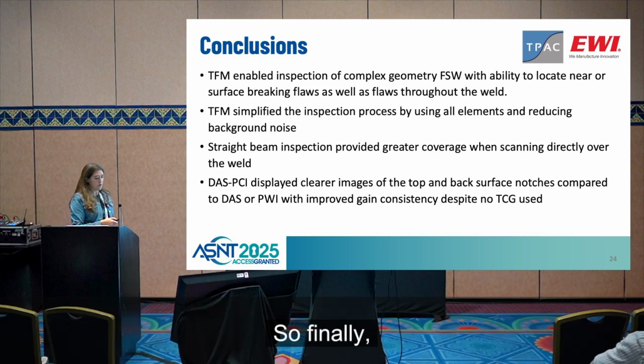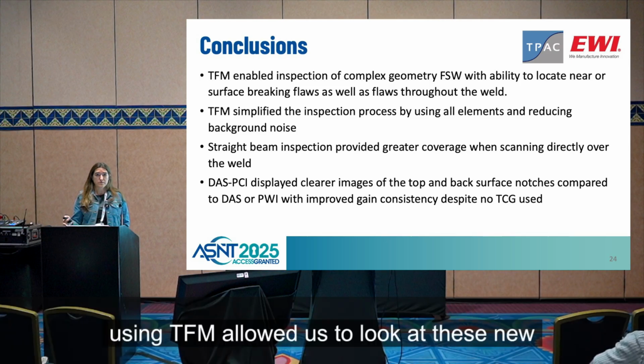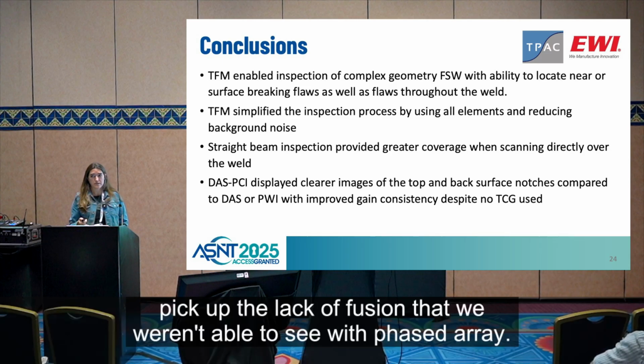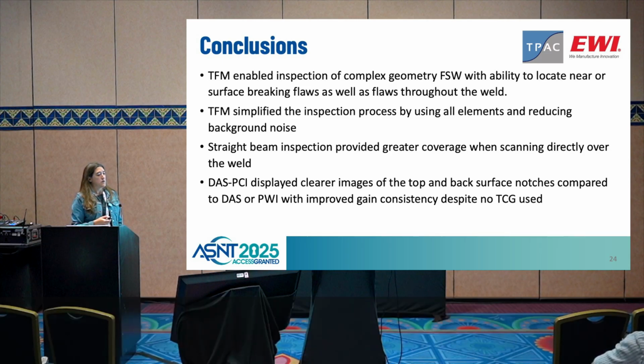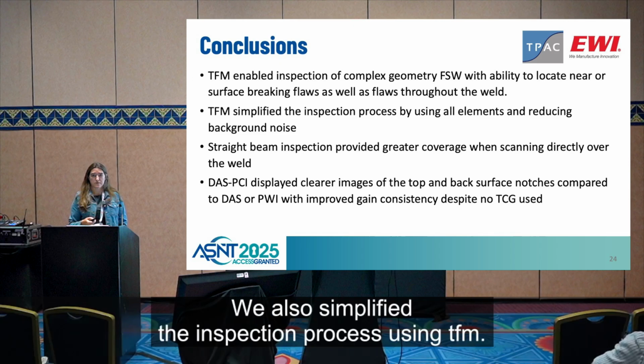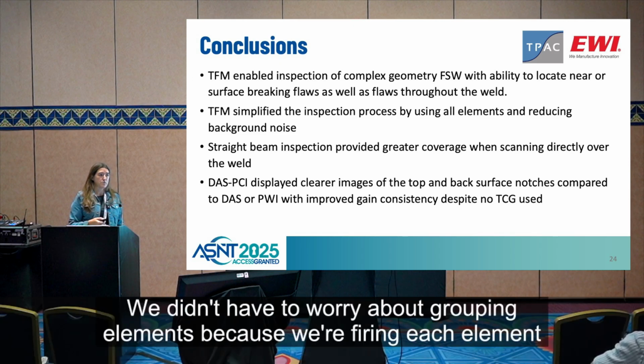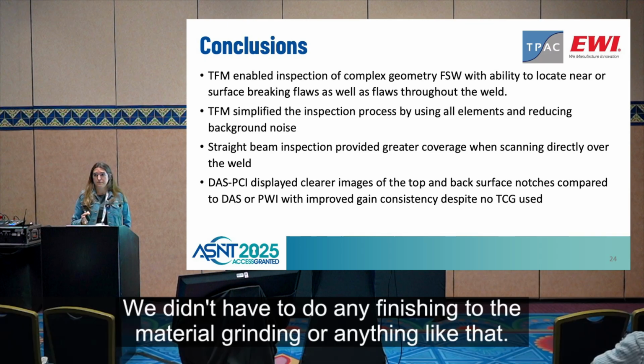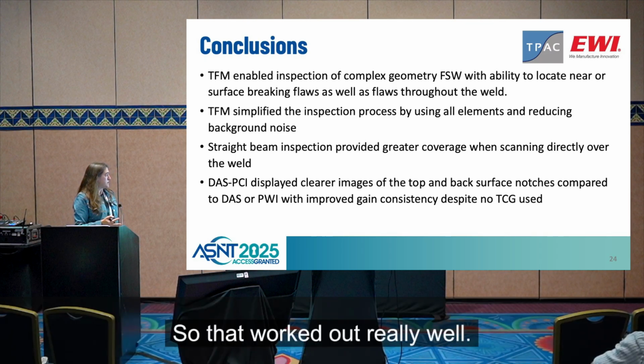So finally, using TFM allowed us to look at these new geometry configurations, scan the entire weld, and pick up the lack of fusion that we weren't able to see with phased array. We also simplified the inspection process using TFM. We didn't have to worry about grouping elements because we're firing each element one at a time and then listening to the reflection with every element. We didn't have to do any finishing to the material, grinding or anything like that. So that worked out really well.